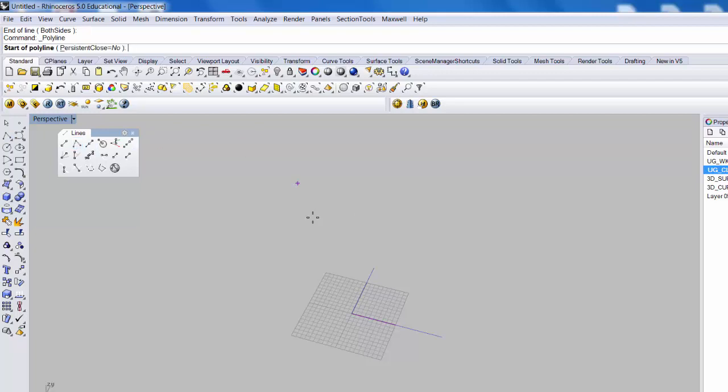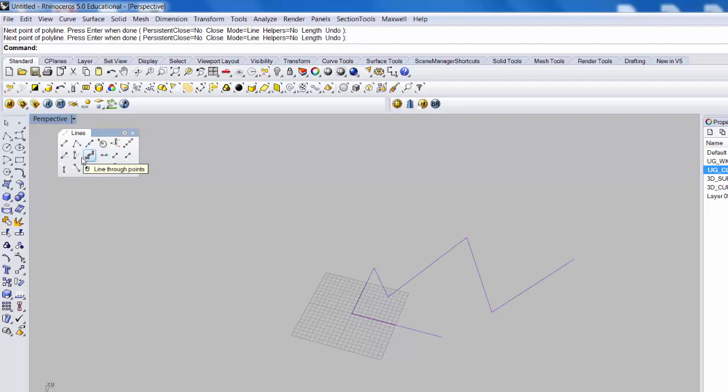So other curves, polyline. I'm going to turn ortho off. We'll let you do polylines. And then there's, so these are all kind of straight lines, and you can kind of play around with different ones. So perpendicular, we'll draw a line perpendicular from another curve. And you can do ones perpendicular to 2 curves, which is kind of interesting. Bisect will actually bisect between 2 angles, and draw a bisecting line.